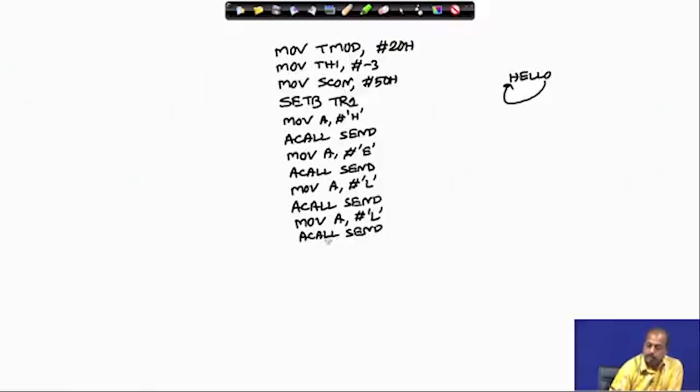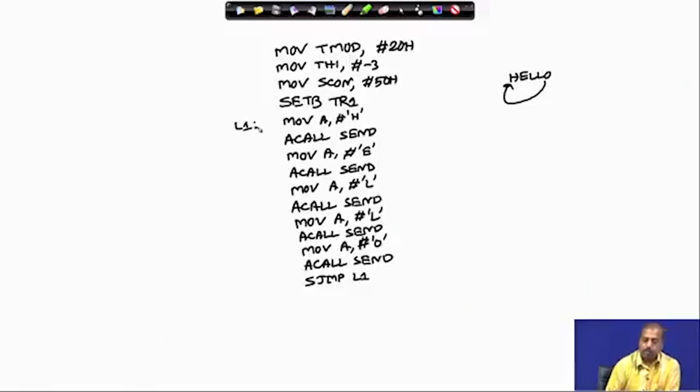Then H E L L O, the O character has to be sent. So, for that we say MOV A, #'O', CALL send. Okay, so that is over, now I have to repeat the whole thing. So, I can say SJMP L1, where at L1 it will start again from this point onwards, MOV A, #'H'.